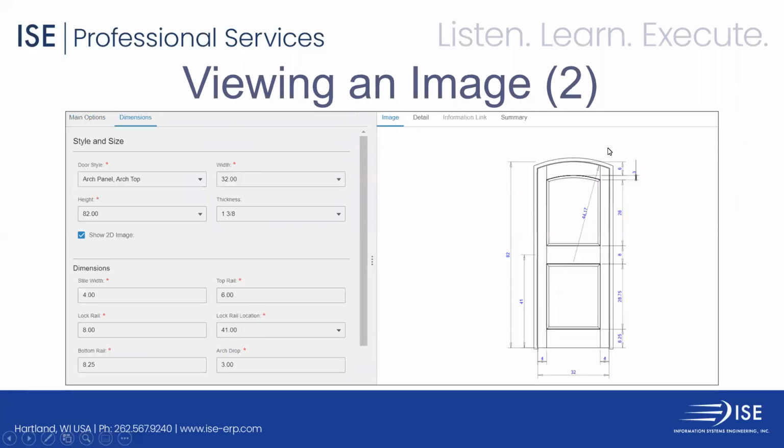Here is a 2D drawing image, and this is a door. You can see it's slightly arched, and it has all the dimensions, and notice how all the dimensions are automatically broken out. And as you change the dimensions, all of those will recalculate. So if you increase the height, then the corresponding parts in the middle will update. So it's now the new height. So obviously it's 82 inches now. If you make that 86 inches, all the constituent pieces somehow have to compensate for that extra 4 inches. Same with the width. So that's an example of a 2D image that's dynamic and changes with the selections that you make.